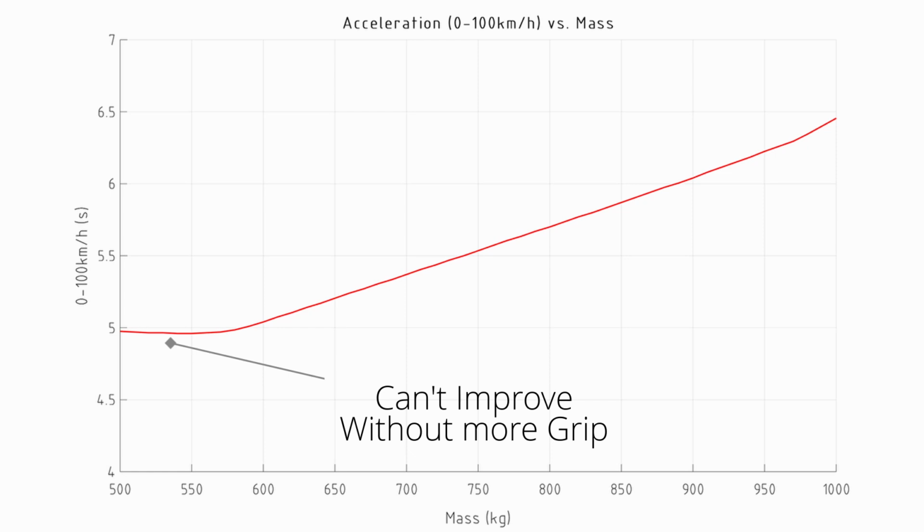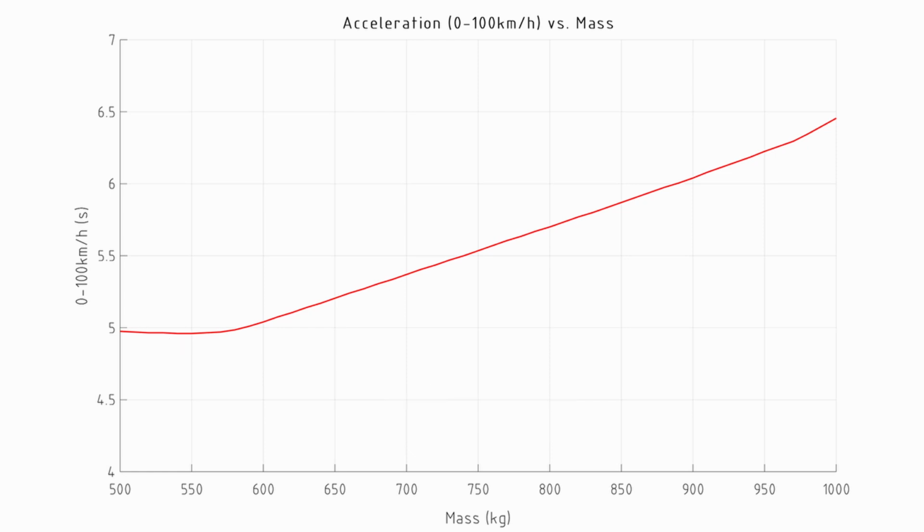If we wanted to improve the acceleration with this lower mass, we would need to have a grippier tire in order to increase our traction limit. Now, some of that will be dealt with if we included some load dependency on our coefficient of friction, but we would still see this tapering off, or this lowering of this gradient, as we get to the lower masses.